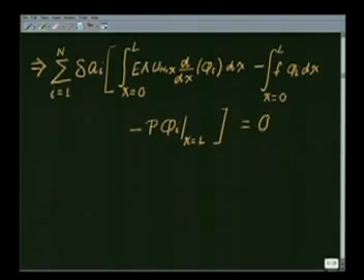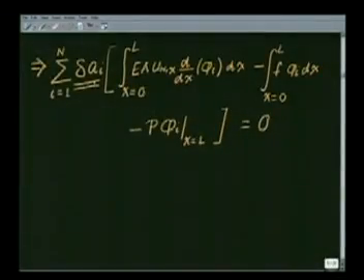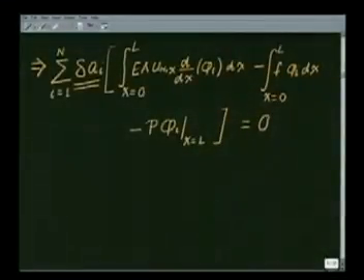Next, how do we get the equations using which we can determine the unknown coefficients ai? That is our goal. So look at this variation of ai. This is something that is under our control. The variation is in a way an abstract virtual displacement that I am giving to the structure, which is already in equilibrium. So I can choose what kind of variation I give. In a way, what I am saying is that we can vary each of these ai's independently, i.e. these are independent coefficients.